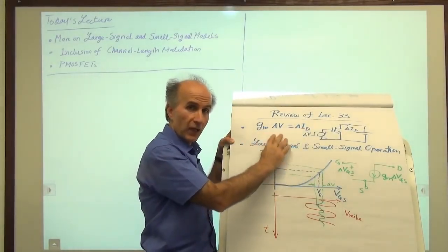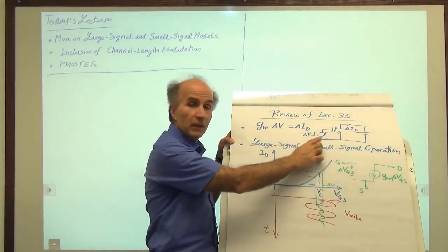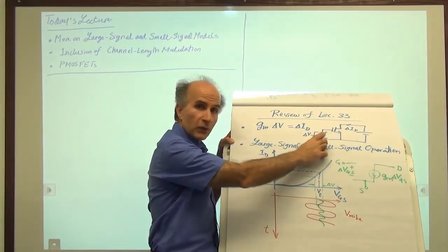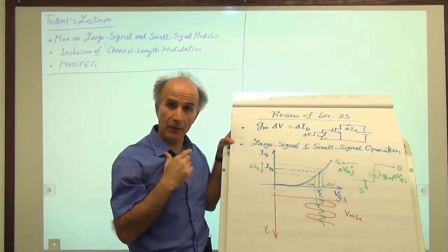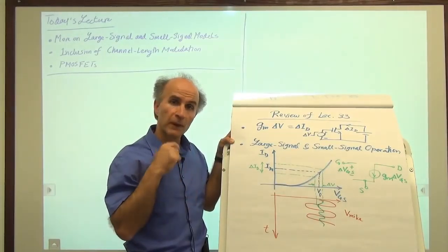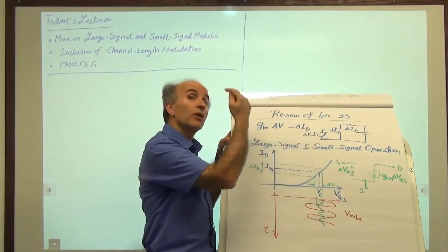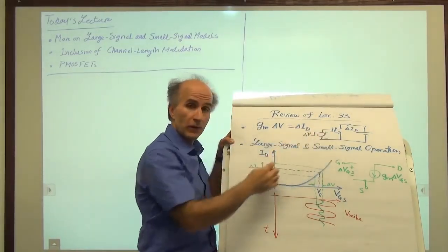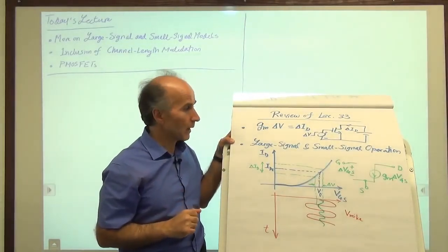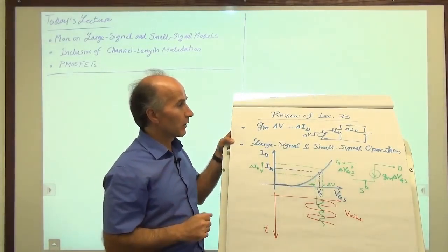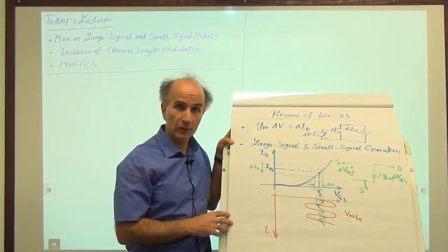So as far as changes in the signals are concerned, we eliminated that battery and we just considered one voltage source representing a change in the voltage. In a sense, this voltage source represents the microphone itself. If I don't speak to the microphone, there's no change in the voltage here. We still have the original battery between the gate and source to bias it up, but there's no signal going in. All right, so based on that, we realized that we can build a small signal model.